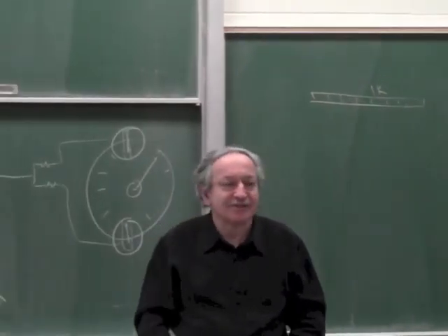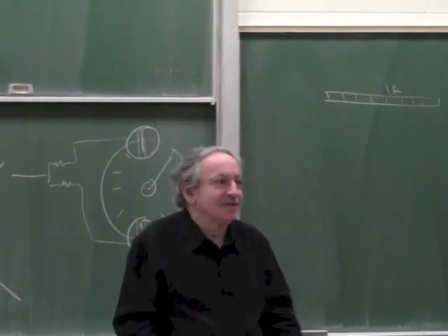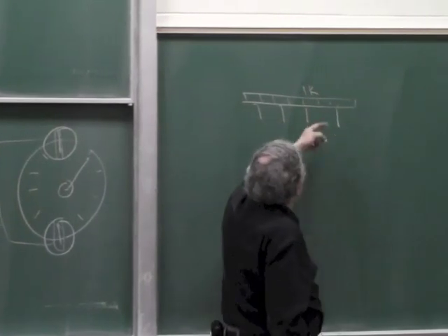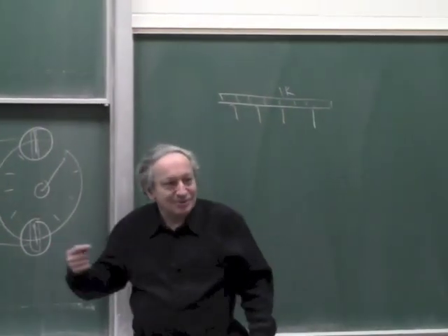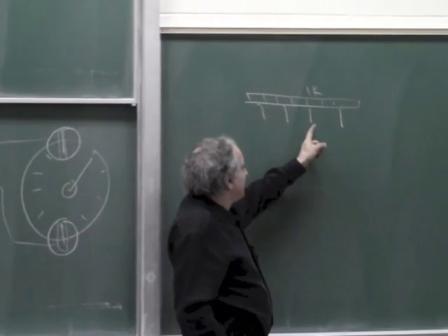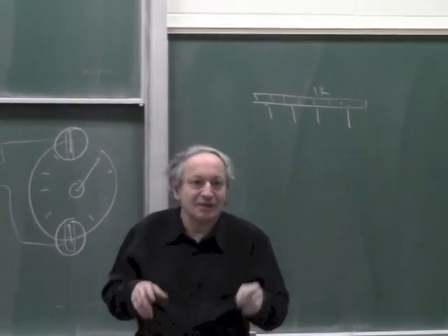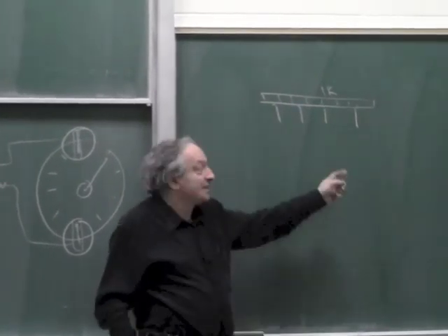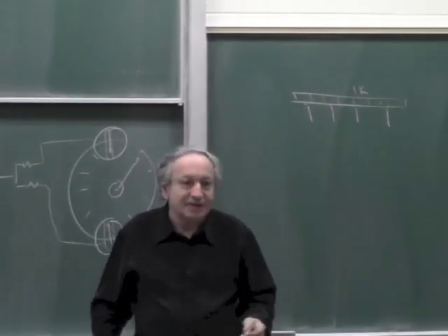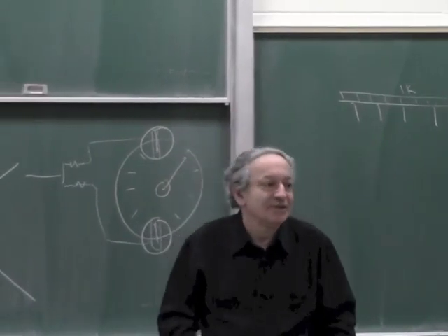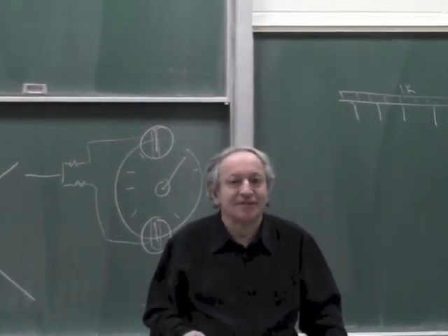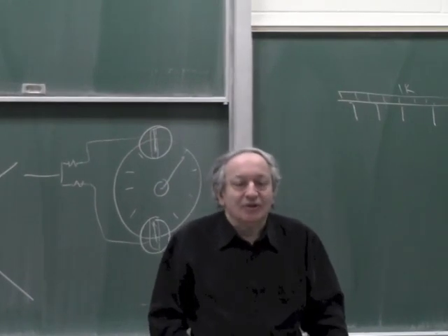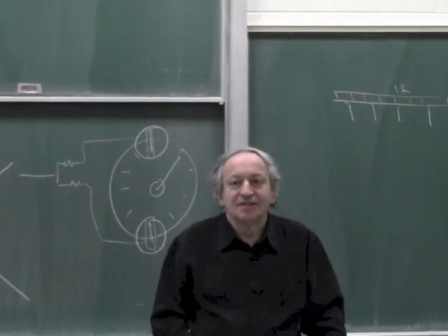And they're very, very fast. They actually have multiple taps so you can get the data out fast enough. Otherwise there will be a bottleneck to get all the bits out. So you get multiple taps so you get the data out in semi-parallel. Every 100 pixels you have an output. And these are standard devices. You can buy those. And that's basically how you do it if you have to measure much faster things with a camera. Okay, so that's sensing with cameras.